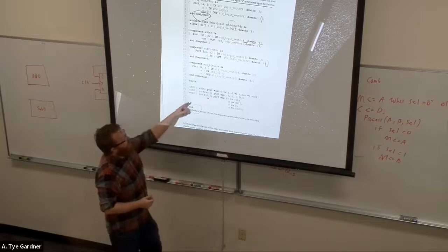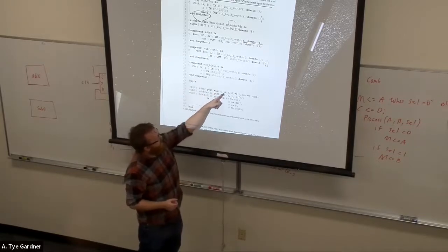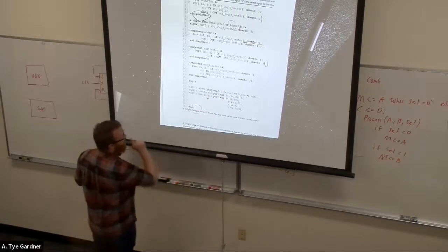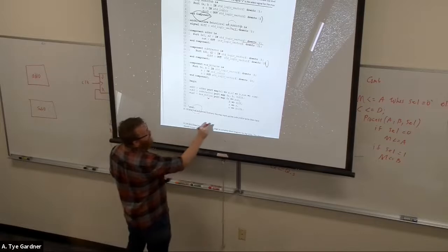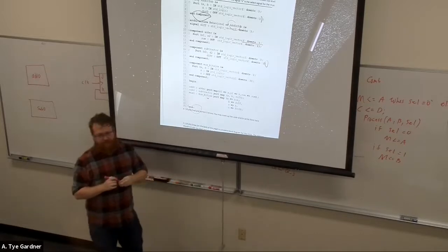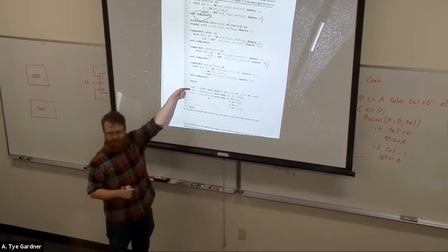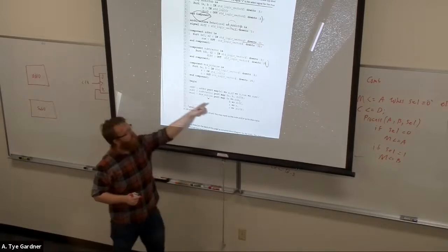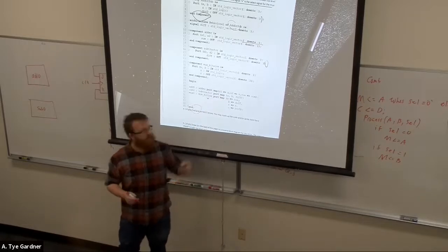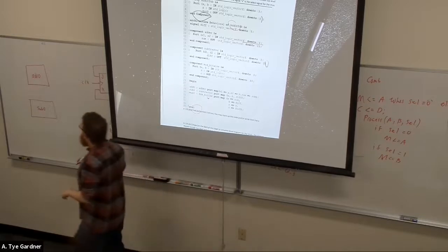So port S1 is an input, and it goes into A. S2 comes from a signal called B. And that same signal A and B come from sub 0. Now, this is actually a little bit of a trick to make sure that you recognize that both of these are perfectly fine ways to create an instance, right? Explicitly mapping it and positional mapping are both fine, right? We prefer this one. There's way less errors that you're going to run into, but we prefer it.